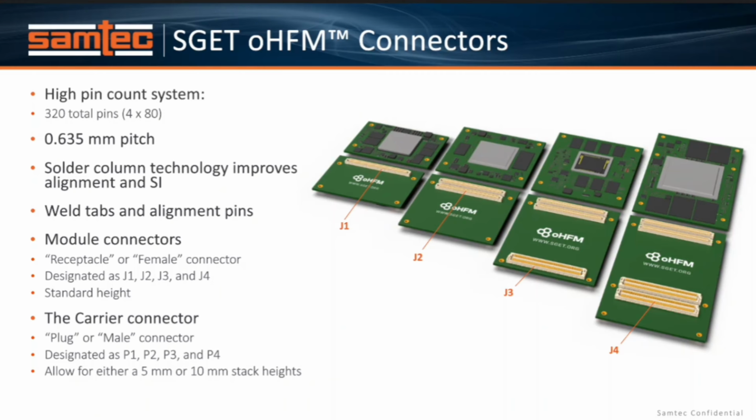Specifically, per the spec, the module connectors are the receptacle or female. You see that illustrated here. In the spec, we label those J1, J2, J3, J4. The module connector, the receptacle or female, has a single fixed height to help simplify processing and to simplify SOM design.